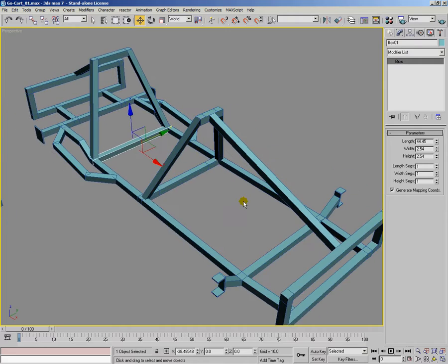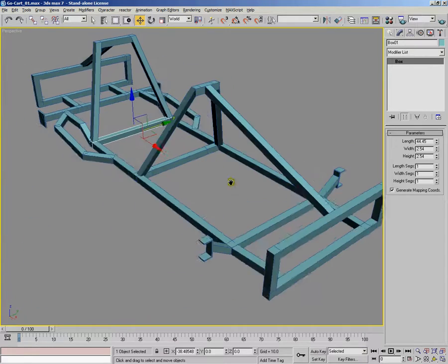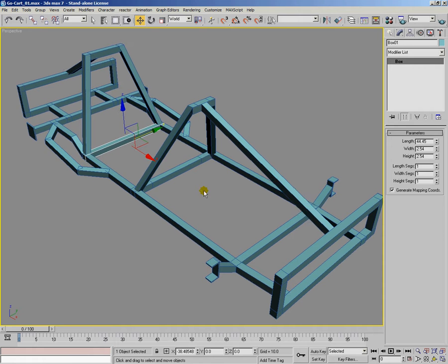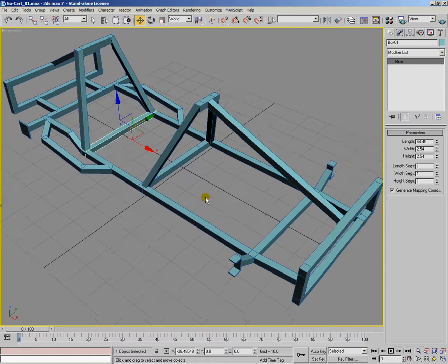And it's important to note that this frame is completely symmetrical, so we're actually going to use that whilst we're modeling. So let's have a look at the grid again. And as you can see, there's a central line of symmetry down the middle of this frame. So that means we only really have to model one half of the frame, and then we can mirror that across and use that as the other side. And this is a common technique when people model, especially mechanical objects. There's usually a lot of symmetry involved. So really, you only have to model one half of the object, and then you can mirror it over to the other side. There may be unique features, but then you can add those as a final stage to your modeling process.